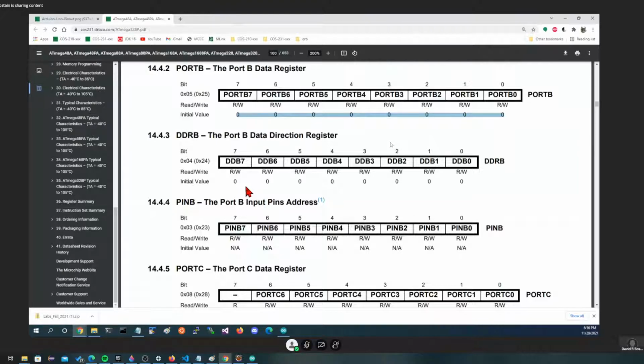So yes, indeed, this is they set the inputs. Remember, inputs, without anything else happening, make it look as though it's a high Z output to anybody else looking at it, although we would be an input able to see anything that changed on the pins. Now the pin is literally hooked to the pins. So there is no default because we don't know what the pins are. Whatever value they have, that's whatever you're going to see if you read the pin. What happens if you write to the pin?